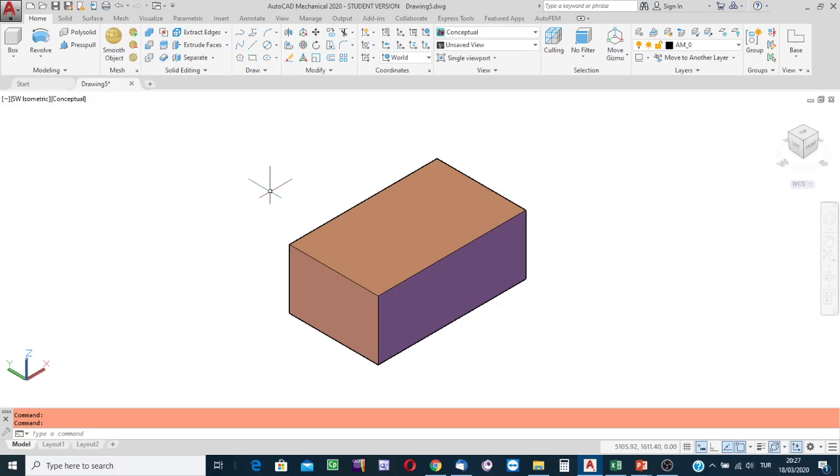Keeping construction lines on the screen is a poor practice. So, to be able to filter the construction lines from the screen, I'm going to create a new layer. You know, layer means transparent paper, and I will have the construction lines in that layer.